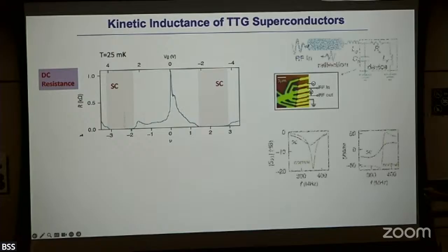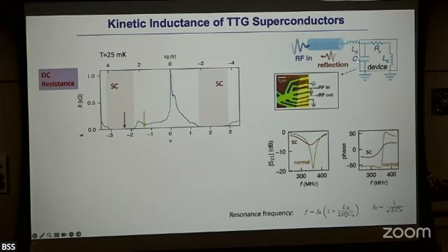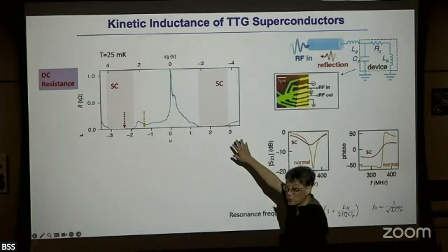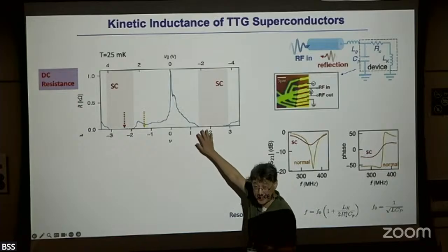Now in this sample we convert our circuits, such that this is my device sitting there. Instead of just doing DC, I send microwaves from outside the fridge, and through this matching circuit I deliver the right amount of power into my device. Note that especially when my sample is in a superconducting state, there is no resistance anymore, and the whole thing is inductive.